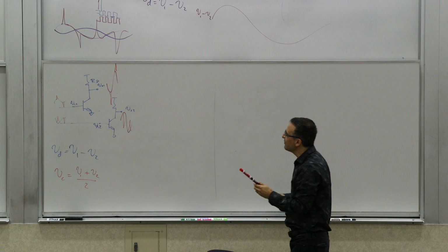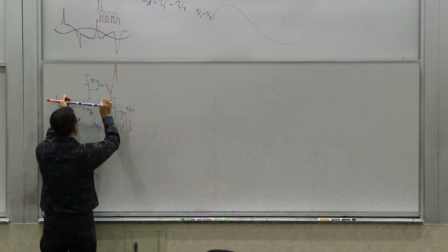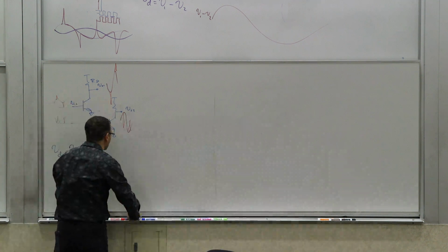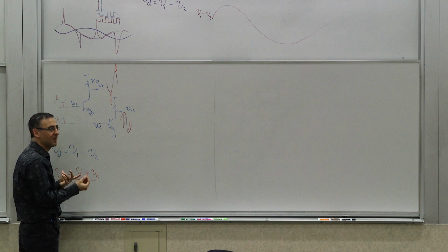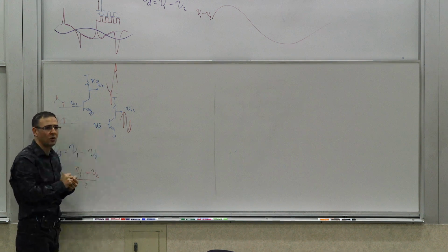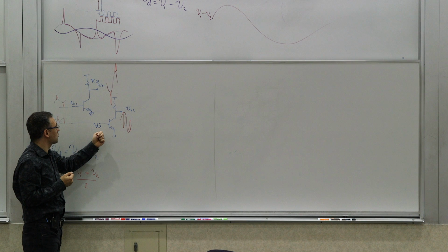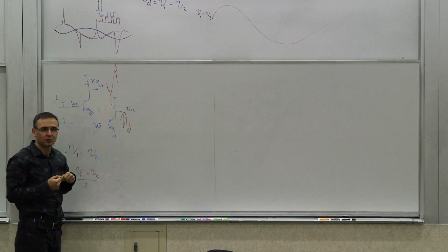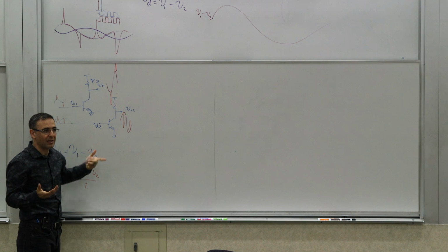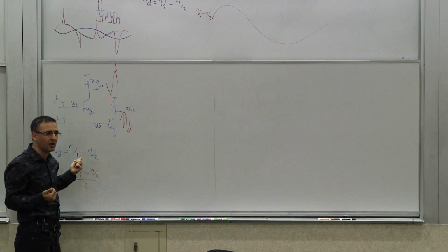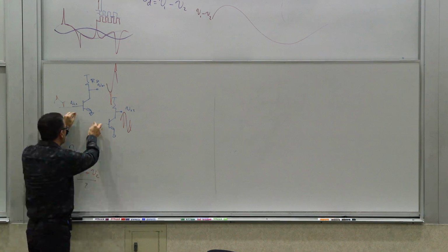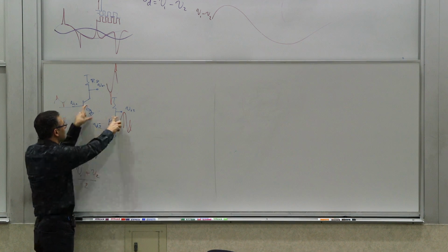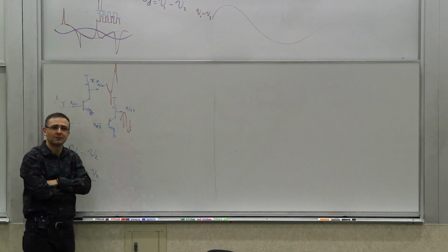So what happens is that when these two inputs go up, you get gain. Why do you get gain? What is the gain mechanism? As this voltage goes up, your VBE is going up, your current is going up, you draw more current through the resistor, right? And therefore you lower the voltage, you get amplification through the exponential. So we want to create a situation that when these two go up together, the total current, the current in each one of them, doesn't go up.